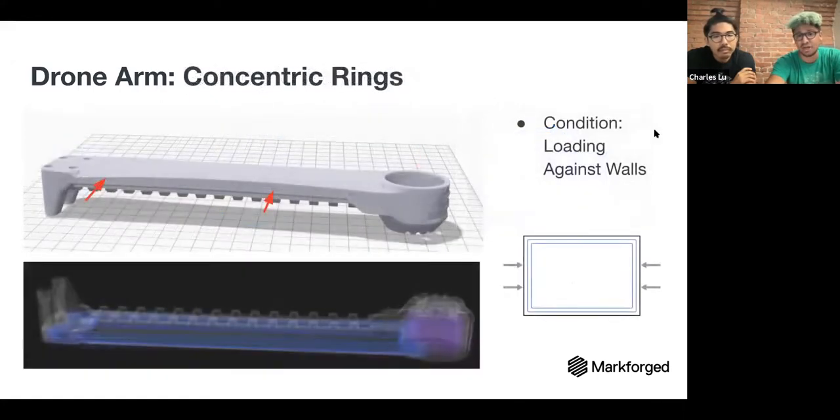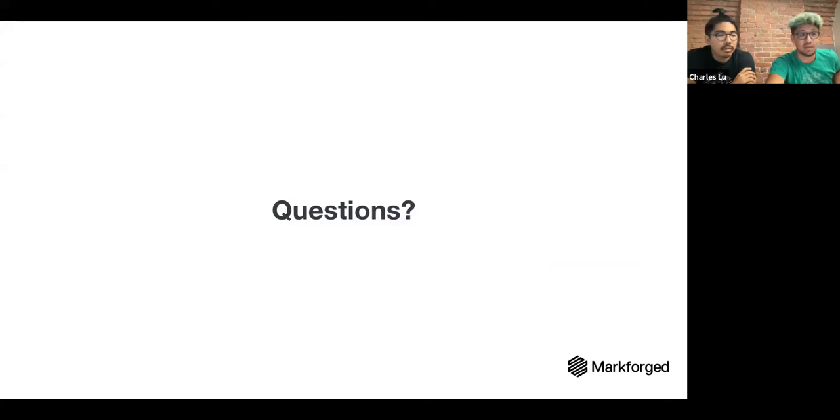And the final tip here is if you ever have any point loads or compressive forces against the walls, adding concentric rings around those walls is the best way to go about that. That addresses anything coming in from the side. If you did have a force on top, then having isotropic patterns would be great for resisting any deformation there, because those fibers will, again, as mentioned earlier, be put locally in tension, counterintuitively to the idea of it being compressed.